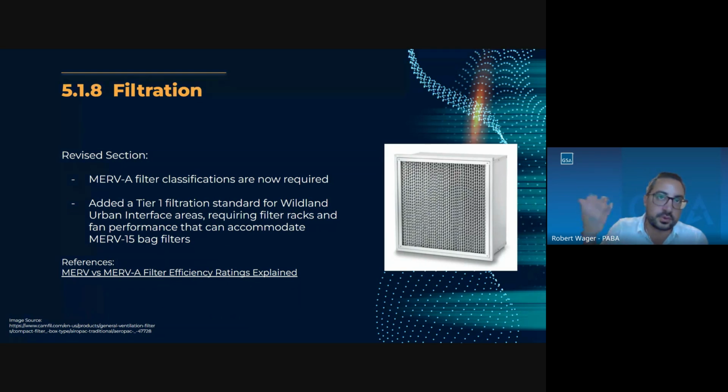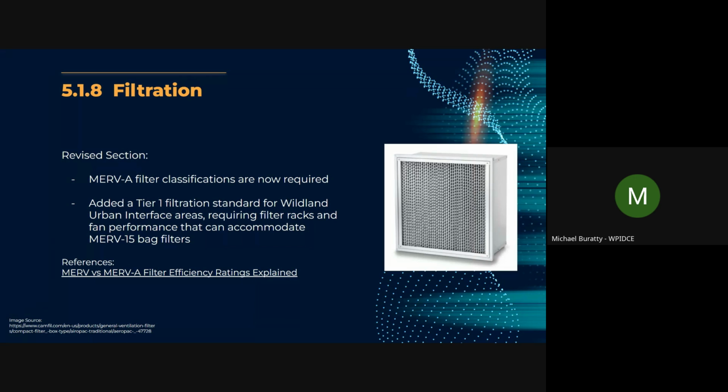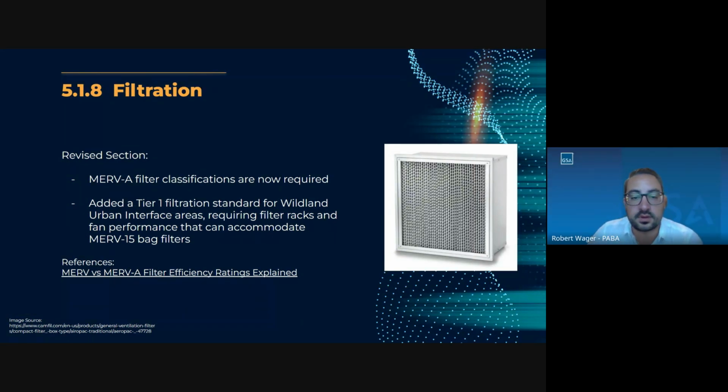So ASHRAE 52.2 puts it through a set of requirements, which essentially is that the filter won't lose its MERV number rating if it's starting to get loaded, whereas non-MERV-A filter classifications, once they start getting loaded, immediately start losing efficiency and start going down. So a MERV 13 filter may not actually be a MERV 13 filter after being used for a little bit.